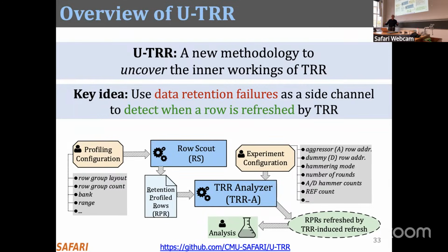You can figure out when they refreshed it. You can figure out how many times those refreshes happened because of the side channel, because you know the retention time of a row. Makes sense? And you can control the refresh rate. It's very simple things that you can control and you can measure, but it gives you a lot of insight into what's happening inside the DRAM chip.